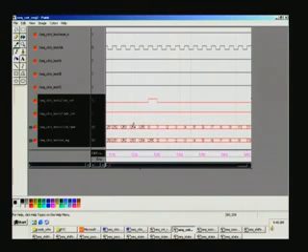That should make it very clear to you. And you can see here the counter edge is 250, 251 and so on. Corresponding to 250 it's a pre-increment, so it is 251, and right at this point of time you notice after 255 the counter next has become 0, and this counter 255 is appearing only at the next clock edge here.